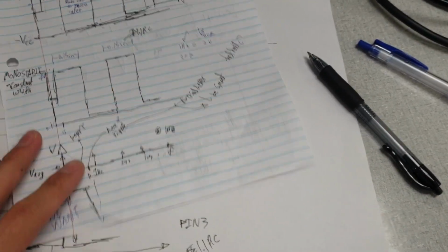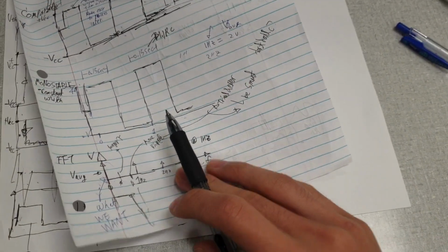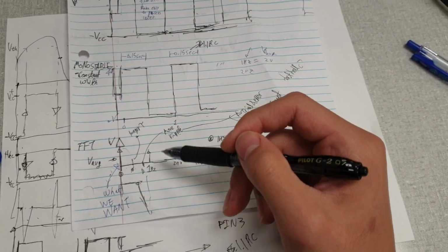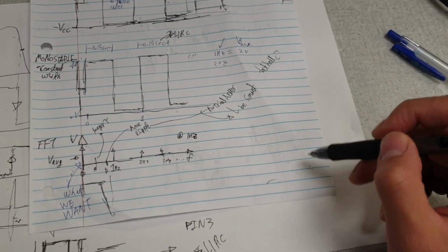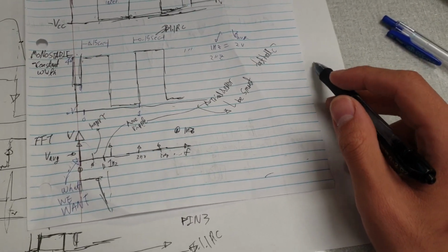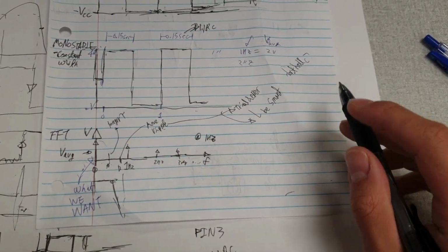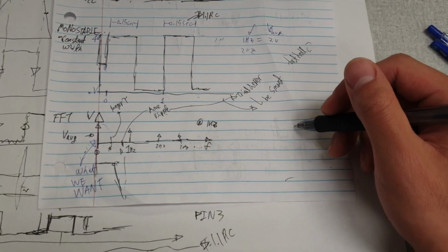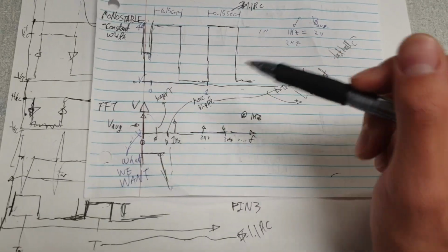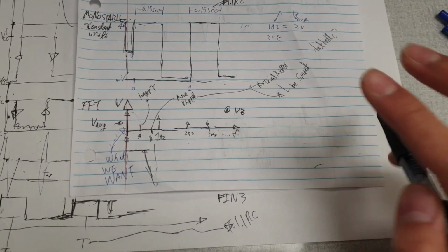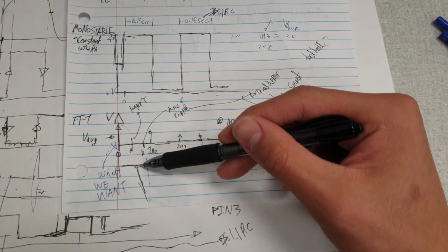After we have this output, we want a DC output, and we can get this DC output by having a low-pass filter, specifically a Butterworth low-pass filter. And in terms of the Butterworth filter, we have to consider a few things. First is the nth order, which is going to determine the slope that is falling down. And the second one is the location of this corner frequency, or 3 decibel frequency.